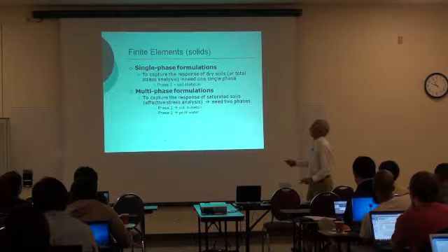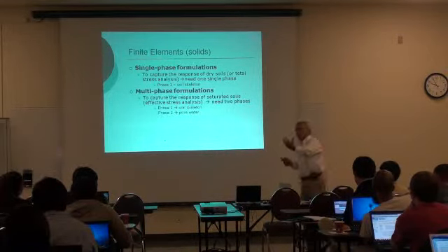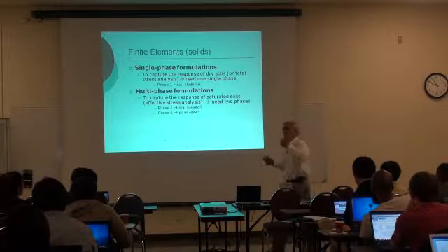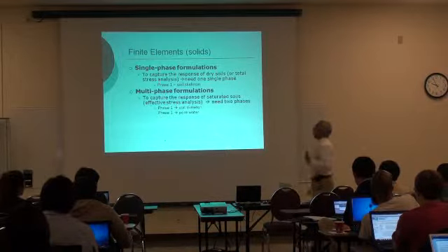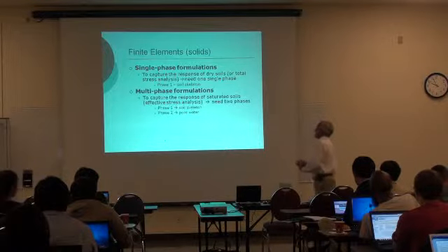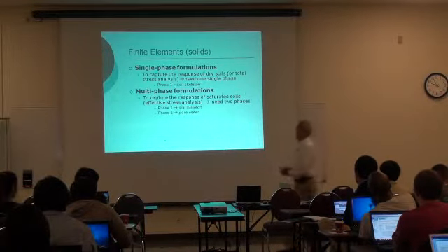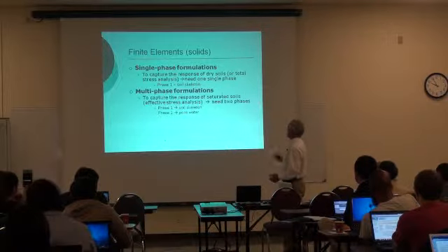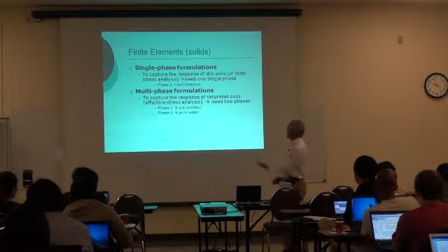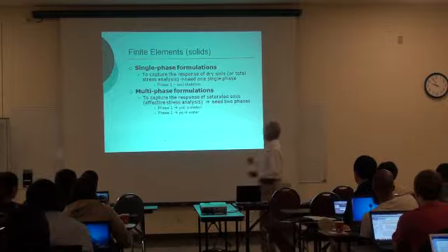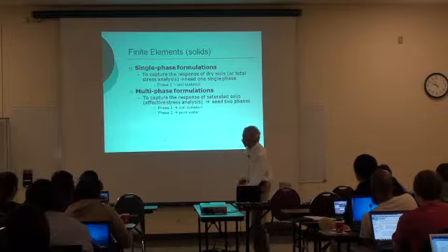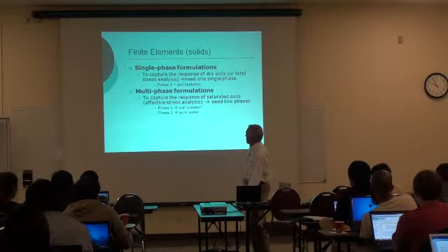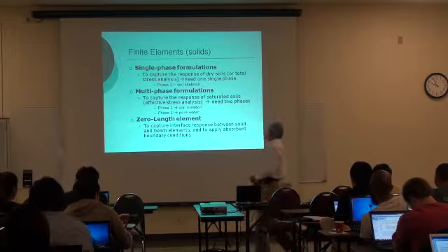Now, in many other situations, you want to separate the behavior of the soil from the behavior of the water. In that case, you need to use a multi-phase formulation that captures the response of saturated soils, and in some cases, even partially saturated soils. For those situations, you need more than one phase. One phase is the solid soil skeleton, and the other phase is the pore water. Particularly when we are dealing with a saturated condition, we need only two. If we want to consider the air, we need another phase also.